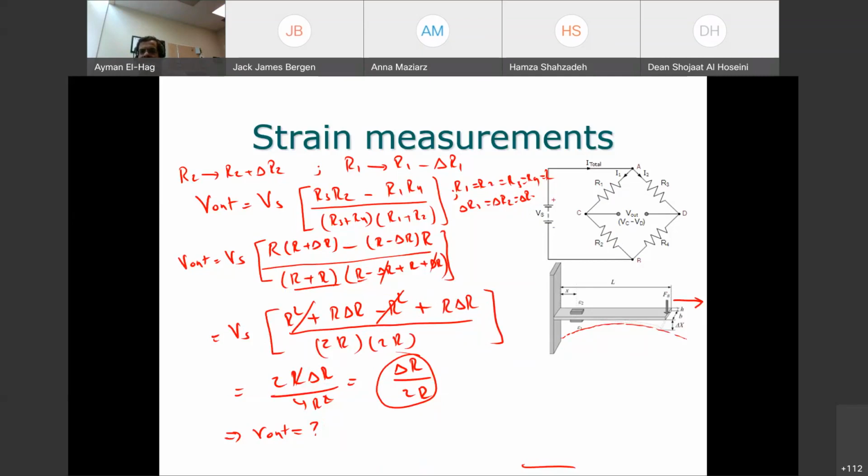Does the strain gauge have to be perpendicular to the... No, it doesn't have to be. The strain gauge is attached as such. So I am now the force. You are right, Carter. Emmanuel, both are correct. So what will happen? Both R1 and R2 will be stretched. Excellent. So is this good or bad?